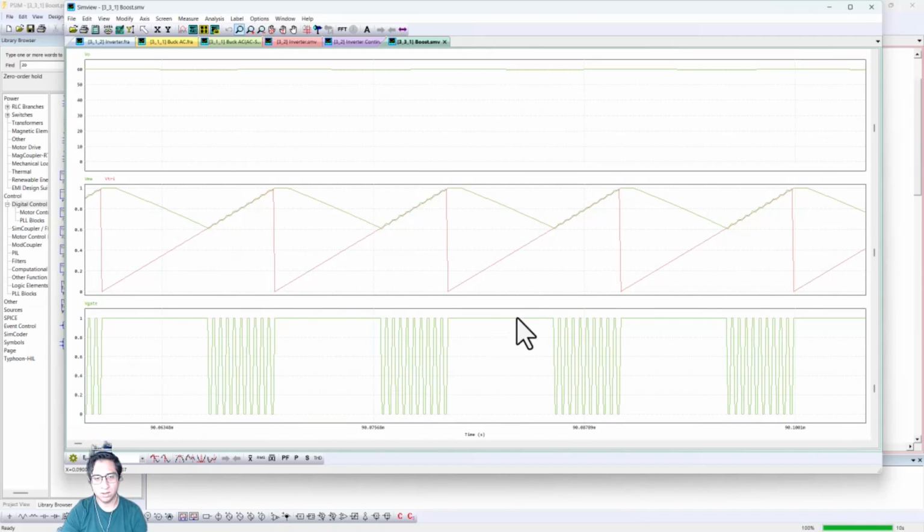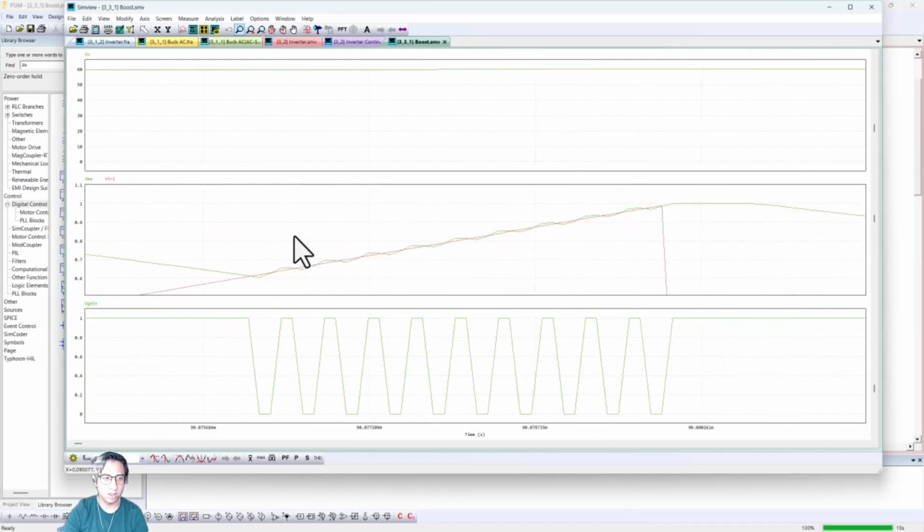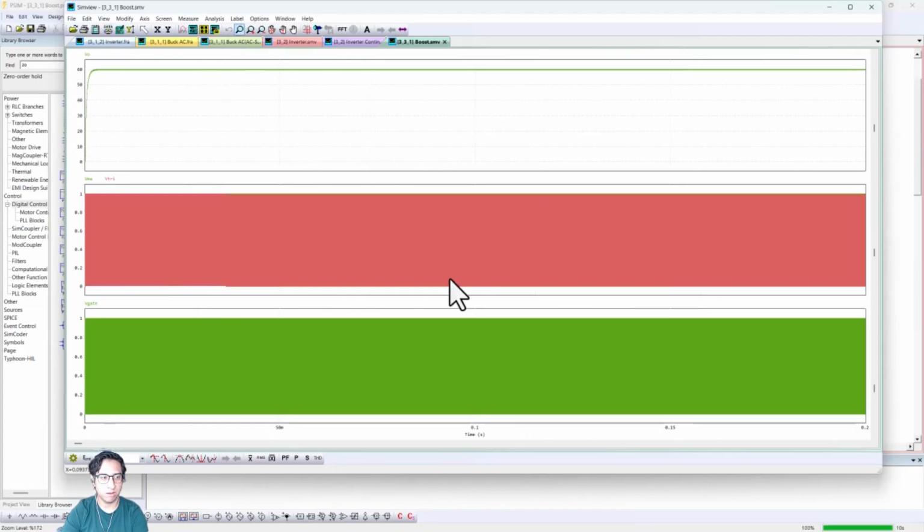And this is because the controller is not doing its work properly. The modulation waveform has a very high amplitude, and it also has this small ripple, which is causing the comparator to actually go in and out of the output value. So it's falsely switching the gate of the transistor, right? So while it might look like it's doing its job, it is not actually doing it so.